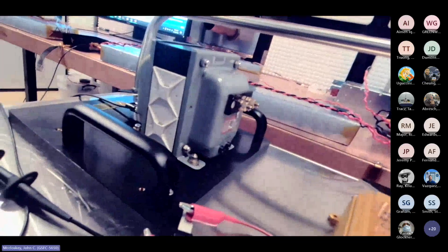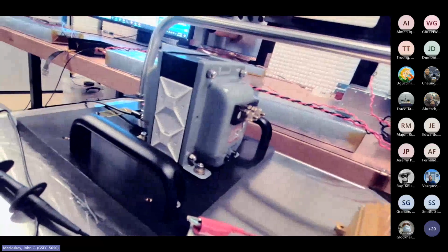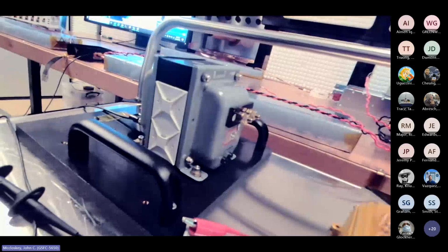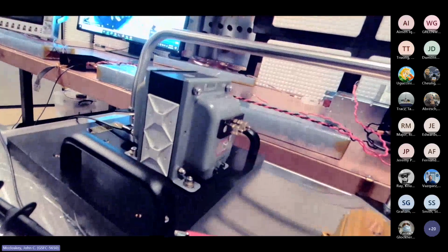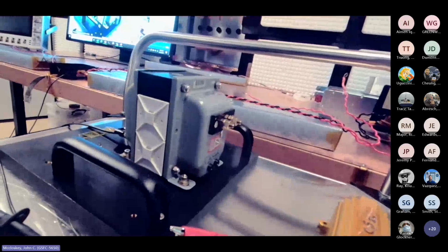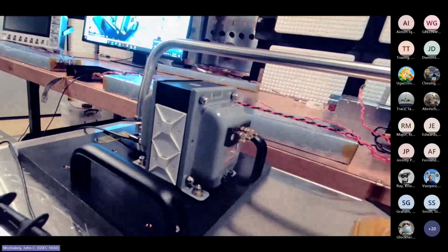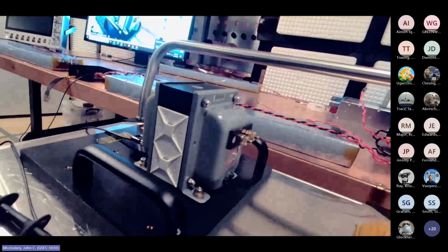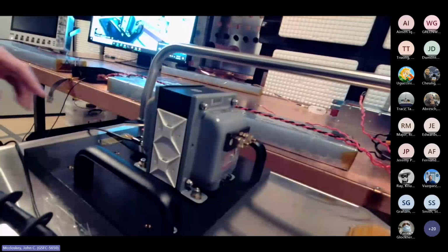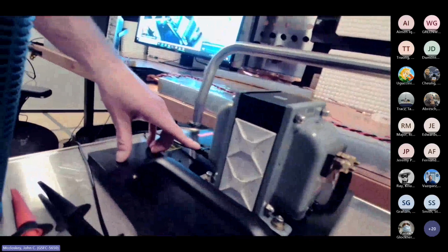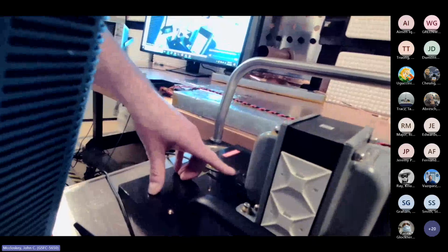Yeah, sometimes, and I don't have it handy, but sometimes we do put a 2.4 ohm resistor on the primary for that reason. And I think sometimes when we left things set up overnight, like if you're doing some CS101 at the end of the day and then you're going to come back the next day, we'll sometimes put a 2.4 ohm resistor module that plugs right here into the transformer primary.